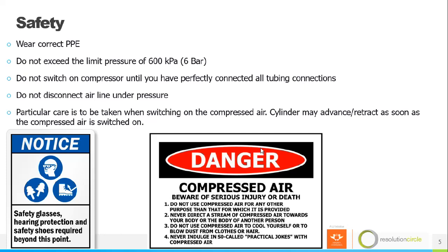So for your safety and the safety of other people, before you apply pressure, make it a point that you check that all pipes are fully and properly connected. And whenever you are done with your system, you should never try to disconnect a line when your system is still under pressure.